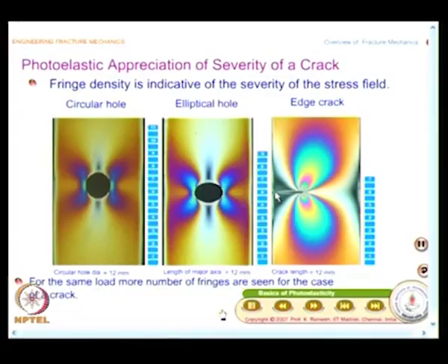mechanics. If you really look at the history, the stress field equations have been improved by looking at the geometric features of the photoelastic fringe. And I have also asked you to look at the special features of the fringe in the vicinity of the crack. Let us look at the features of the fringe. This is the crack, and we will take this as a reference axis. About this axis, the fringes in the top and at the bottom are symmetrical. The other striking feature is the fringes in the top are tilted forward. Keep this geometric feature in your mind.